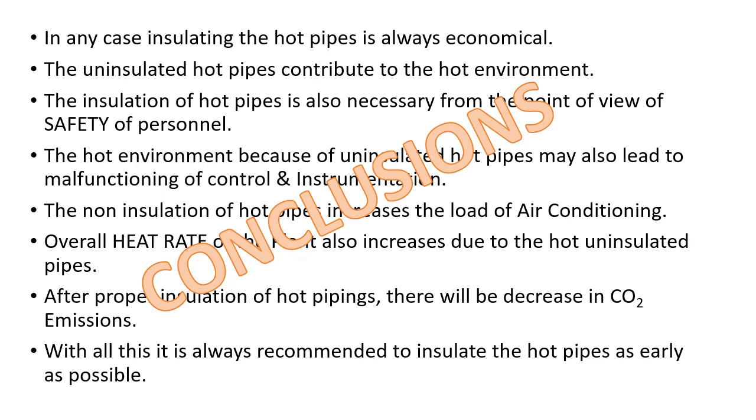The non-insulation of hot pipes increases the load of air conditioning. The overall heat rate of the plant also increases due to the uninsulated hot pipes. After proper insulation of hot piping, there will be a decrease in CO2 emissions. This point is also important, which may be noted. With all this, it is always recommended to insulate the hot pipes as early as possible.